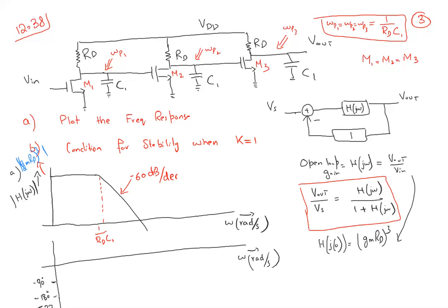This is not drawing down, but it will be something down here. So if we want to draw at 1 over RDC1 where the cutoff frequency is, this means at that point we have minus 45, minus 45, and minus 45. So overall minus 135 at this point. So it will start from some point, 10 times of this one, which is basically 1 over 10 omega p, which all are same. So it will reach this one,